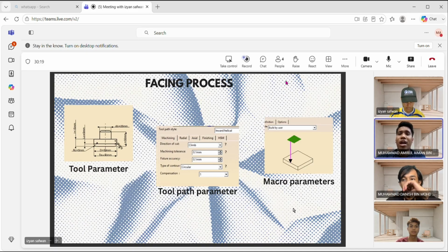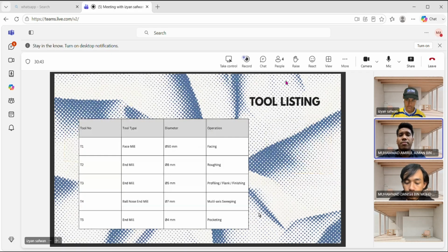Now, I will explain the CAD model and machining setup. First, the curved guide block was designed using CATIA V5 Part Design. Since this component contains complex curved surfaces, it requires multi-axis machining to achieve better dimensional accuracy and surface quality.